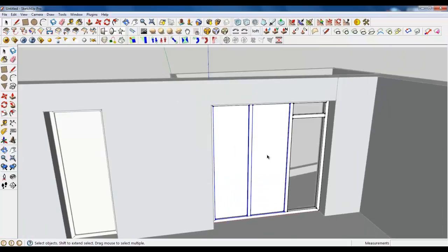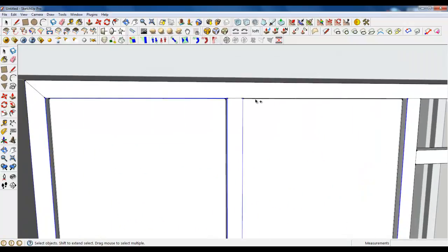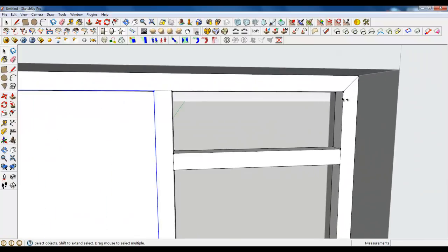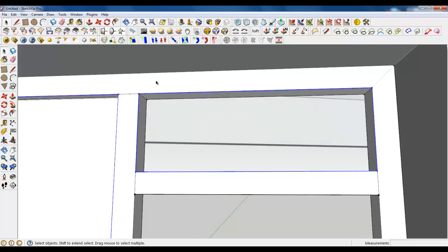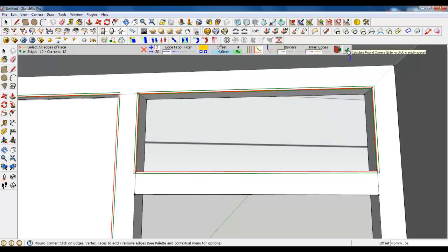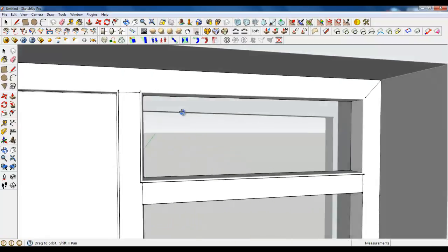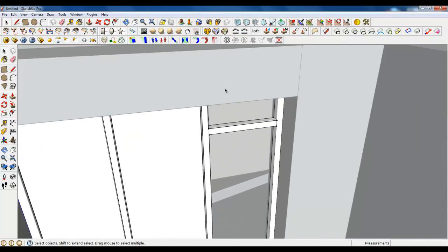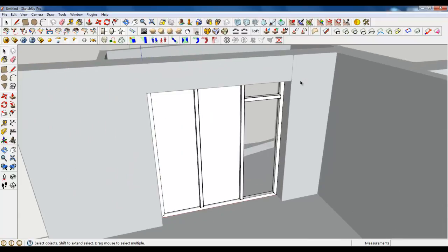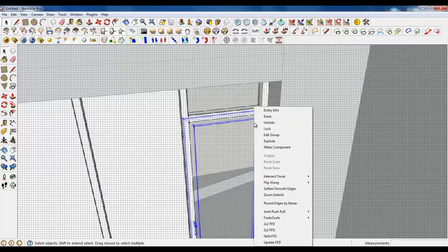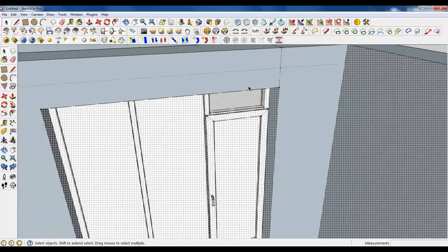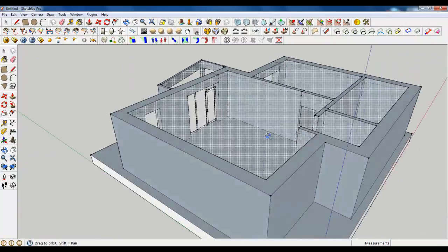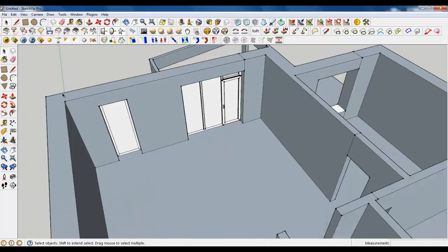I'm doing it now. Well, it's easy, but it takes some time from you. And well, I have no words. It's real simple. Selecting lines and telling the program to do everything. It's done now. So unhide the doors of the balcony, and now you see a grid all over the screen, because it's a hidden ceiling, so just turn off hidden geometry.